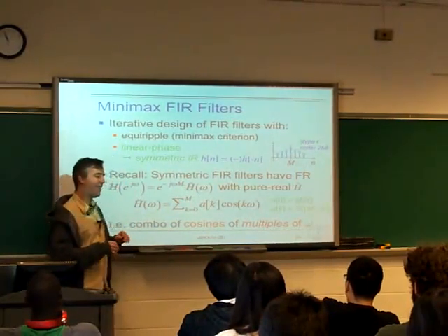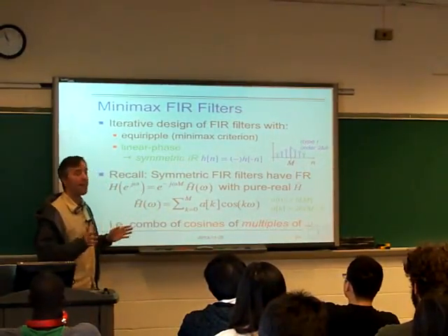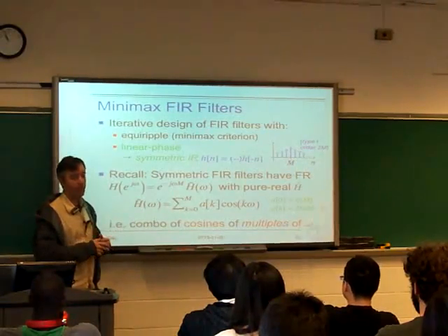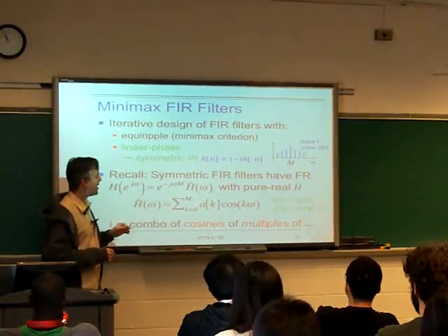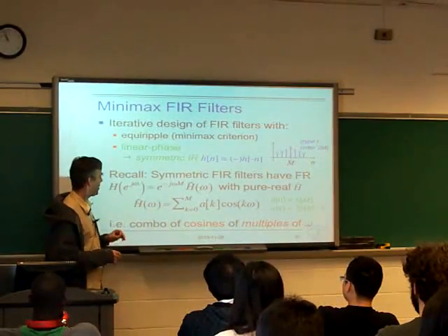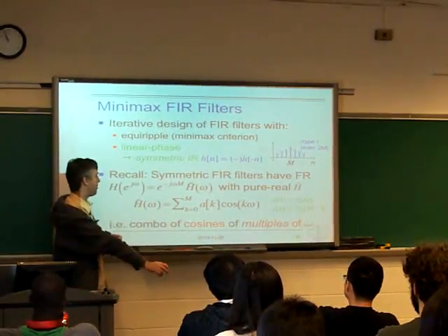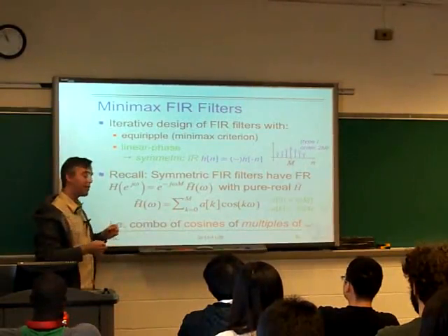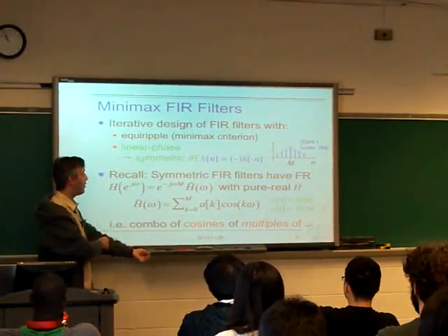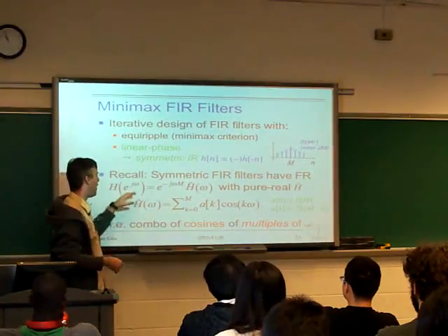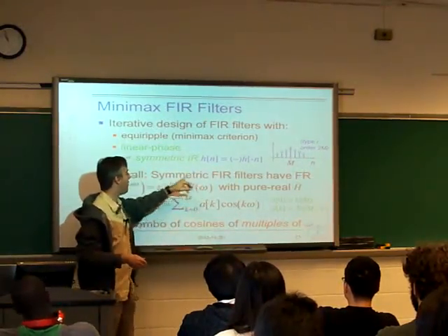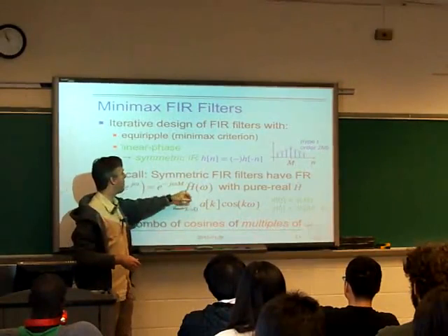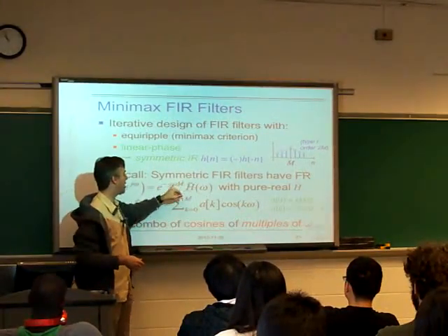Now, that's basically all we need to do. We can just plug it into our favorite optimizer and we get an answer out. But it's worth looking a little bit below the surface here, just to see what happens. When we looked at linear phase filters before, we found that this symmetry in the impulse response allowed us to write the frequency response like this as a pure phase term. This is the linear phase term.